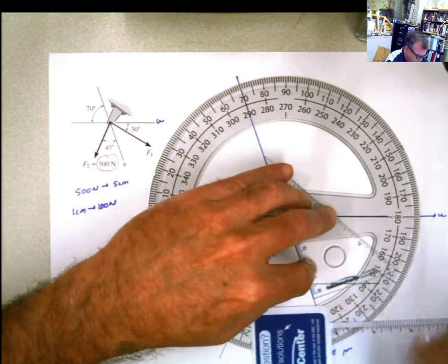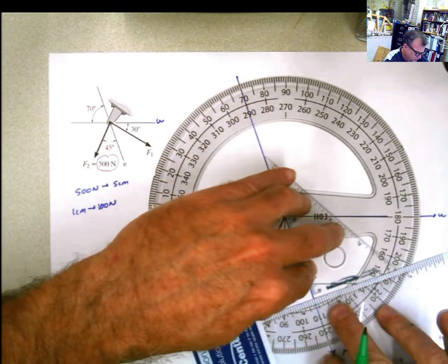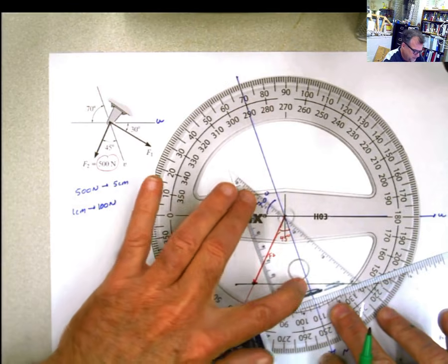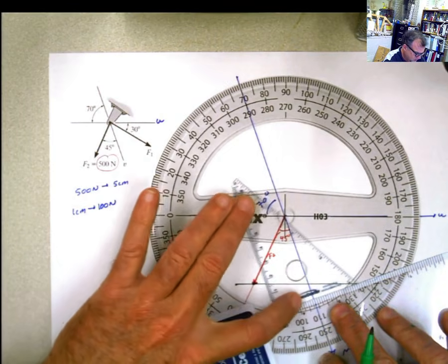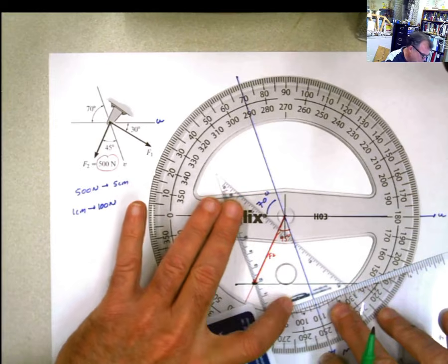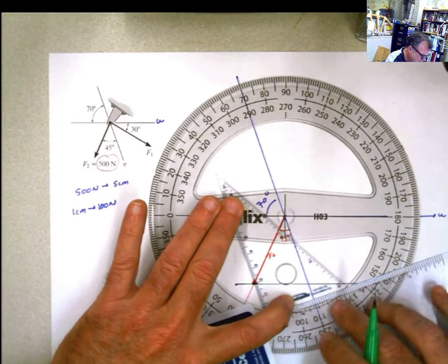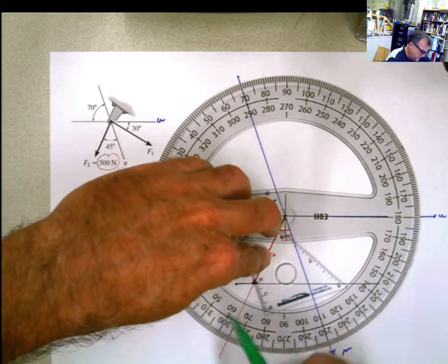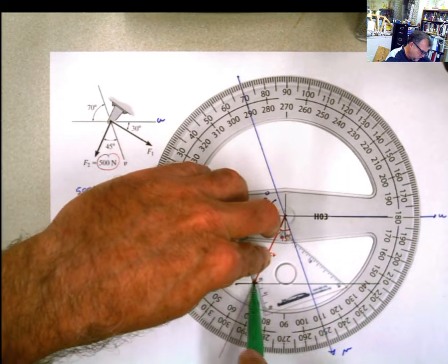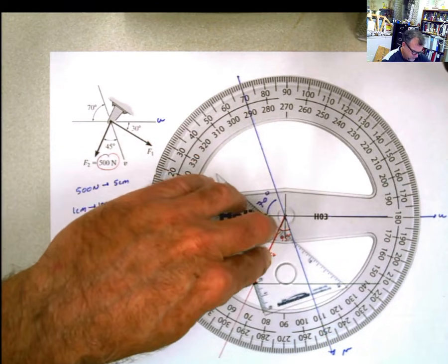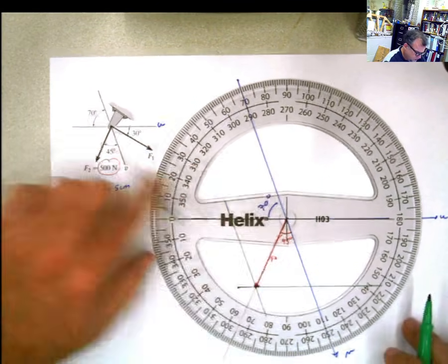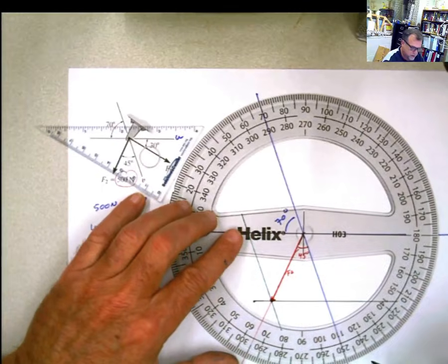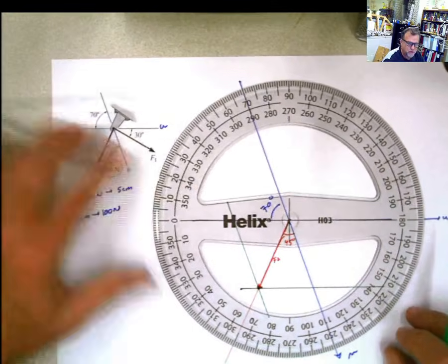Now you put the other ruler here, and now if you slide this, you can make lines parallel to my v-axis. And once again, I'm going to make that line coincide with the end of that point. So I'm going to draw a line here parallel to the other axis, to the v-axis. And if you realize, what we have done here is that we have created a parallelogram. You see that parallelogram there? Basically those are going to be the components of that force.